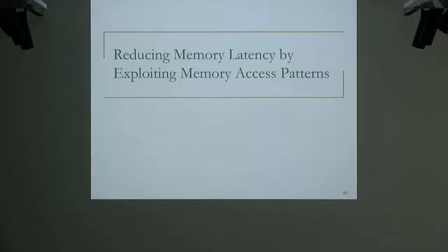Okay, so let me not switch gears, but we're still talking about reducing latency. I'm going to give you another way of reducing latency, which, if the DRAM is built without a lot of internal timing assumptions, shouldn't require changes to the DRAM itself. Unfortunately, existing DRAMs are built with some timing assumptions internally, where they're self-timed. As a result, you cannot do what I'm going to describe in existing DRAM chips, but there's no reason why you cannot do it if you don't have those timing assumptions internal to the DRAM chip.